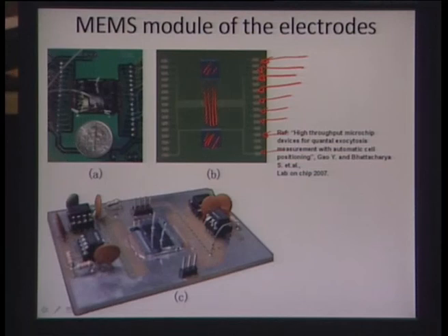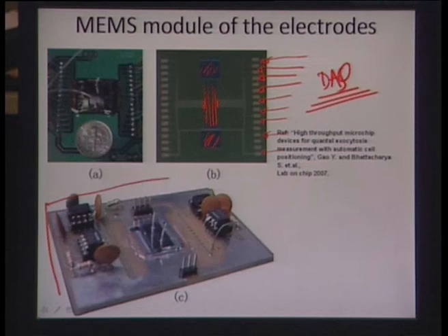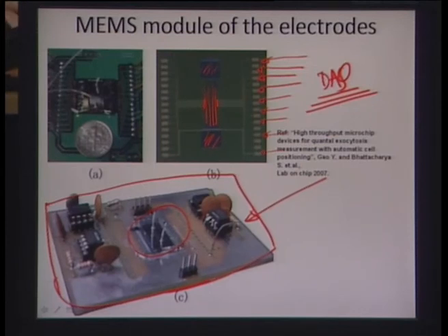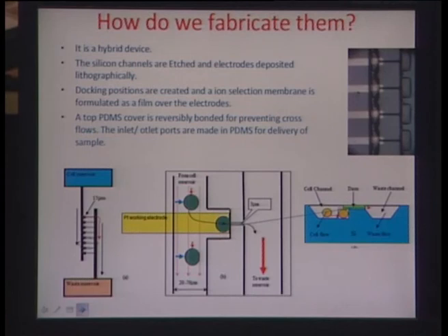and so there is a flow of cells and positioning of cells over these individual channels or electrodes, and the ion exchange resin here can be coated, spin coated selectively using photolithography on certain specific areas where these electrodes interact with the solution of interest, okay, and can be rapidly recorded using a DAC system, a data acquisition system, and so all the electronics can be built surrounding the particular chip here of interest, and this can be a bio-MEMS device to measure electrochemistry of a single cell.